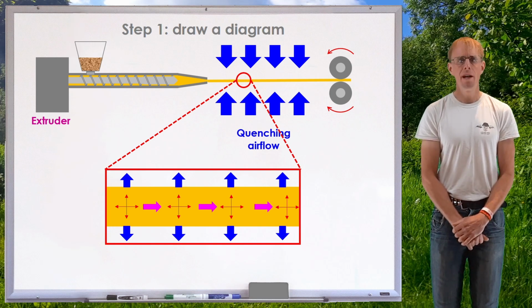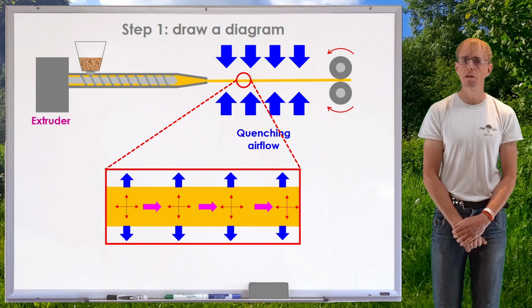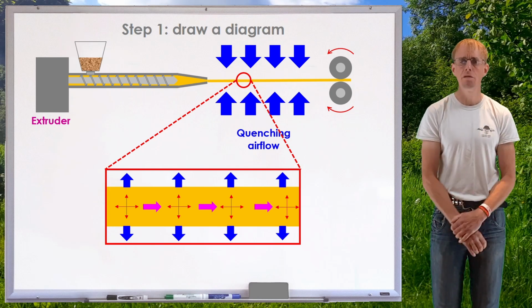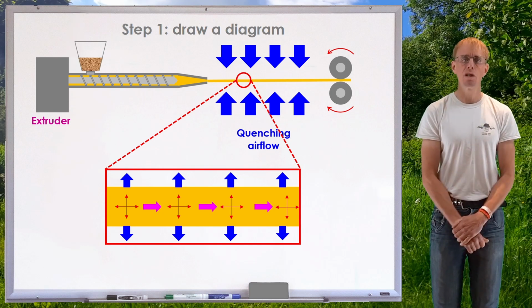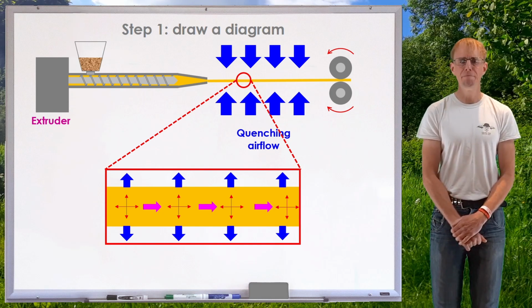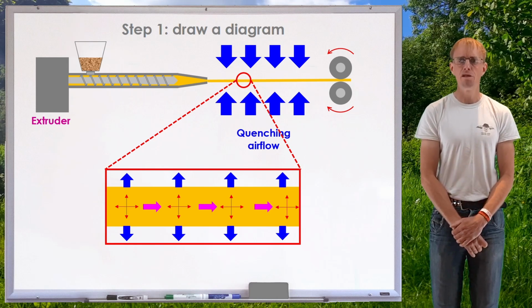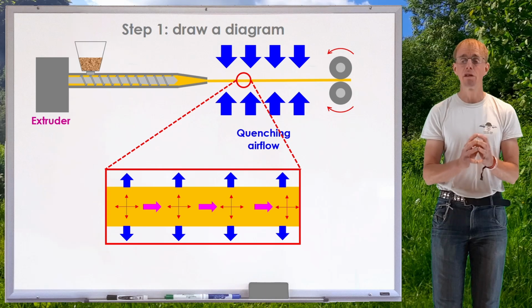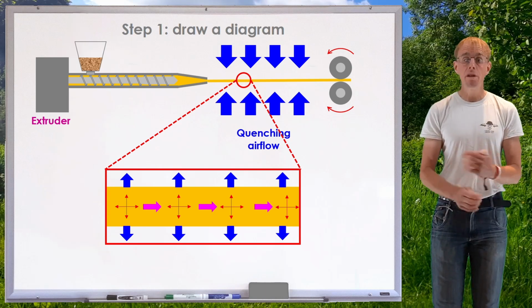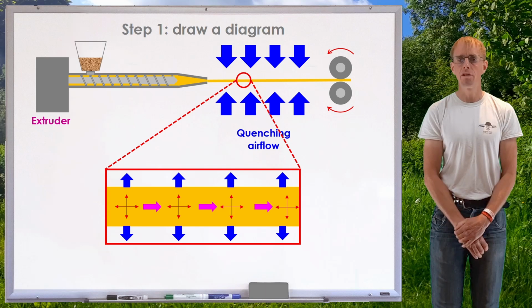And so if I think about non-dimensional groups here that might be useful, the Peclet number might be instructive at some point, advection to conduction. The Biot number might be useful, external convection by internal conduction. And this will give us a feel for what's going on in this heat transfer scenario. But at the moment what I've got are these three modes of heat transfer, and sometimes one of these modes is going to dominate over the rest, so I may be able to simplify the problem quite nicely.